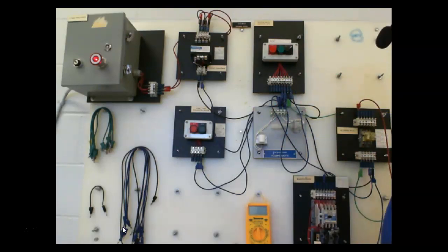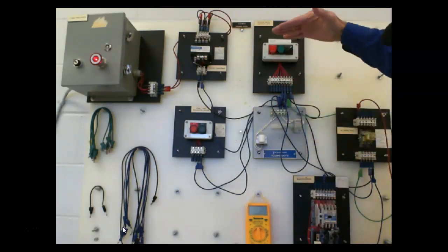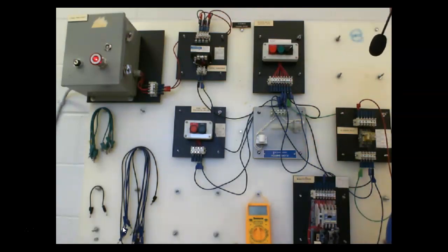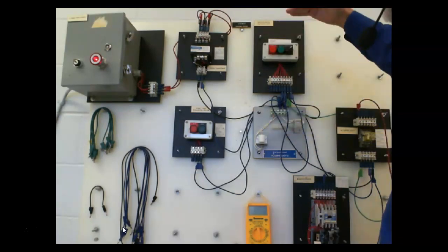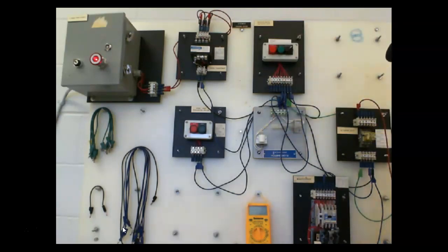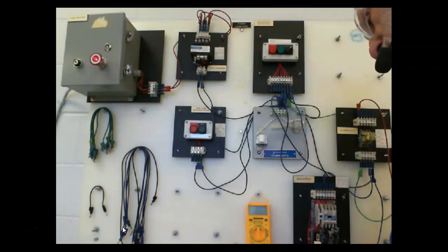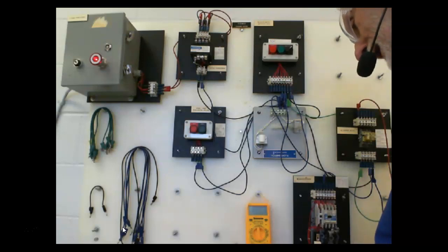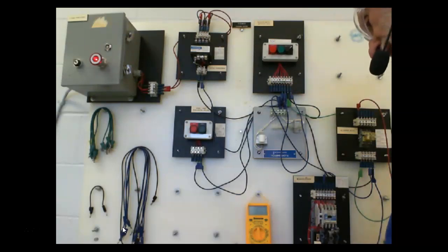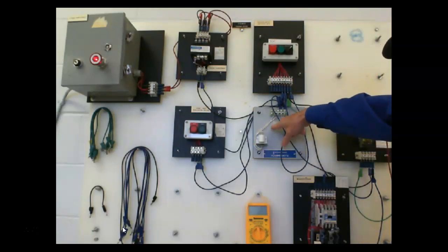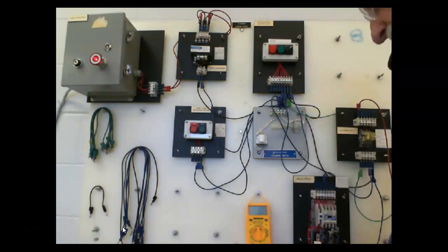Yeah. So I think I told y'all wrong. The level switch would actually be at the top of the tank. I think I told y'all the bottom when I was wrong. Simulate the level. So that was A11. Then A12 says simulate the level switch detecting a rise in the level by activating the level switch. Did the motor stop? Okay, it stopped. And of course, if it drops down, it'll start.